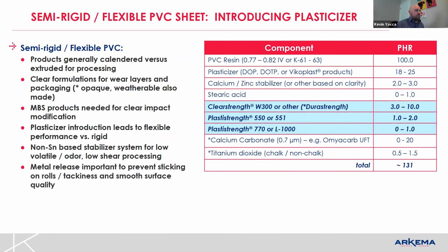When I take that all the way back to the Brabender, it really just matters what your consistency is. So if you are comfortable that the compounds you use and the range of formulations you use will always be within, say, 65 grams for a rigid weatherable formulation to add to a Brabender that I see a lot, right? That's always somewhere around 100 cc's, and that you're not going to deviate much more than 0.2, 0.3, 0.4 grams away from that, no matter what you do, then you can add 65 grams every time.